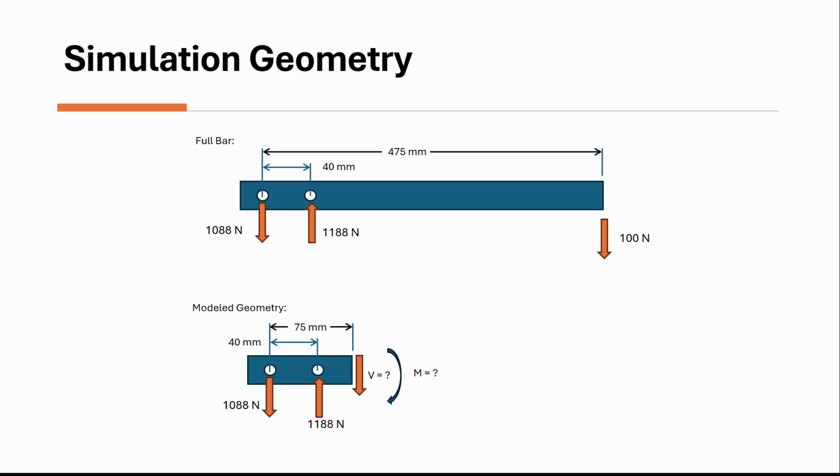As a planar bar, its cross section is 20 millimeters by 5 millimeters, and it's relatively long, over basically half a meter long, and I don't really want to mesh the whole thing just to look at the stresses around the holes where they're going to be highest. And so what we could do is trim this off and put on statically equivalent loads using St. Venant's principle, and then analyze it, and we should be able to get out some good estimate of the results or the stresses in those regions.